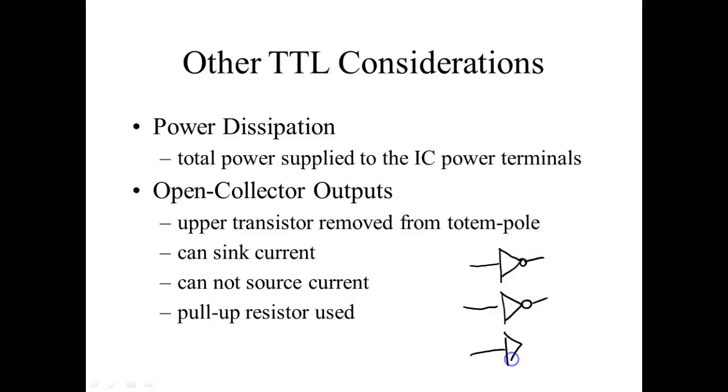I'm going to put 3 gates down here, and I'm going to connect them together, right? Is this good or bad? Well, this is bad. Okay. So we'll use standard series. These guys here can source 400 microamps, and they can sink what? 16 milliamps. Okay.